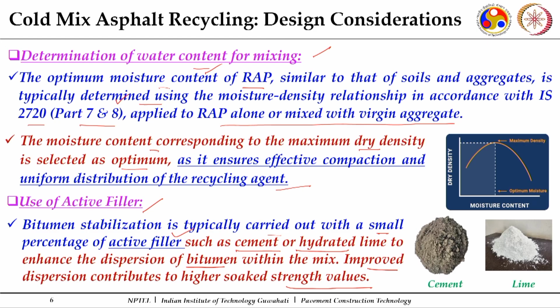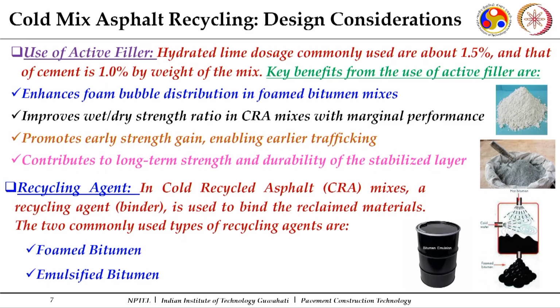So we need to look at the incorporation of active fillers along with this water content part. As I mentioned, the typical percentages used may vary depending upon the RAP gradation. The typical contents are 1.5% for hydrated lime and around 1% for cement.